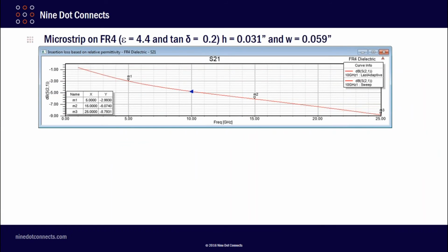So here's what we have on the S21, again on a 4-inch piece of material, which is not very long necessarily for some high-speed designs. So when I picked my markers at the fundamental frequency, the 3rd harmonic, and again at the 5th harmonic. Remember from the very beginning of the slides, we had to have those 3 components to create a fairly valid square wave. So you can see the losses that I have on my S21.